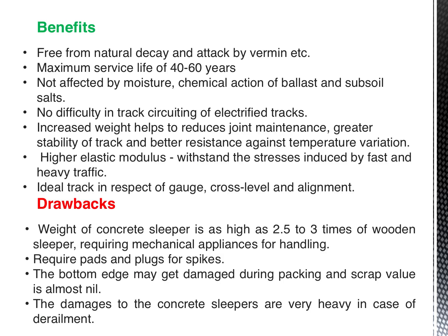When you look into the benefits, we have a lot of benefits with concrete sleepers. Anyways, concrete sleepers are the ones which are mostly used. These are free from natural decay and attacks by vermin, unlike wooden sleepers. They have a maximum service life of 40 to 60 years, and are not affected by moisture or chemical action of the ballast in the subsoil. And there is no difficulty in maintaining the track circuit, because concrete is a bad conductor of electricity. You can easily maintain the track circuits.